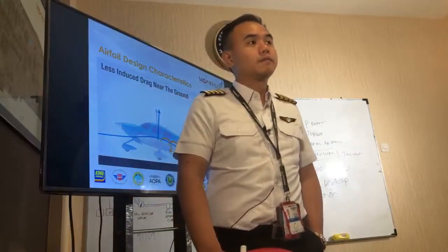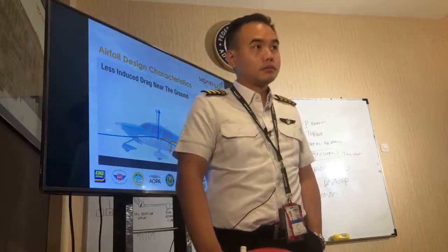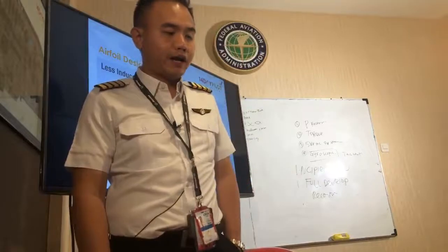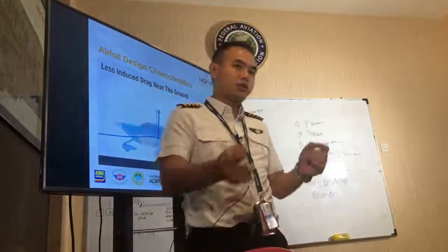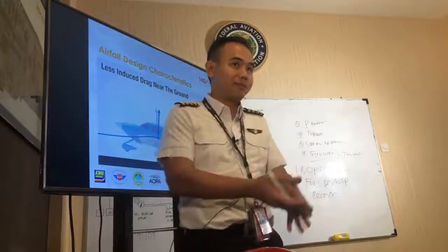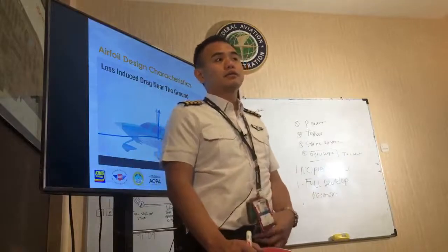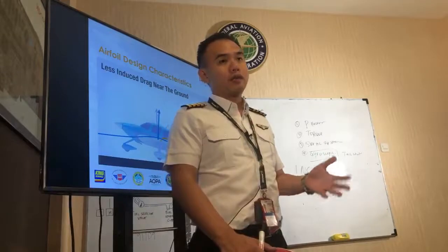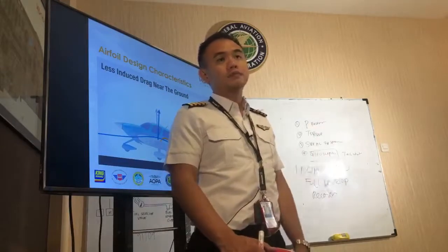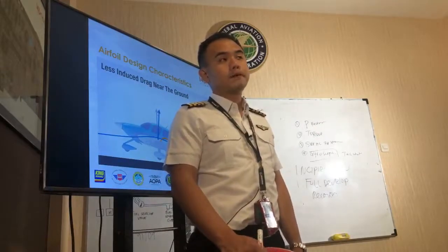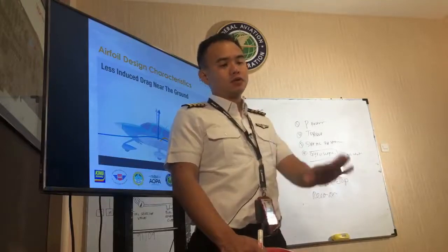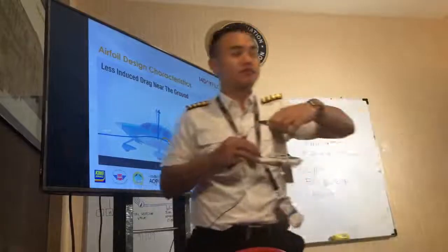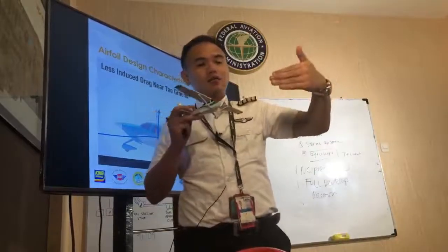Should we do that in crosswind? The Airplane Flying Handbook teaches us to do yoke into the wind and opposite rudder. That's actually slipping the airplane. There are two types of crosswind technique: crabbing, and one wing low. If the wind is coming from this left side, your airplane will be like this.